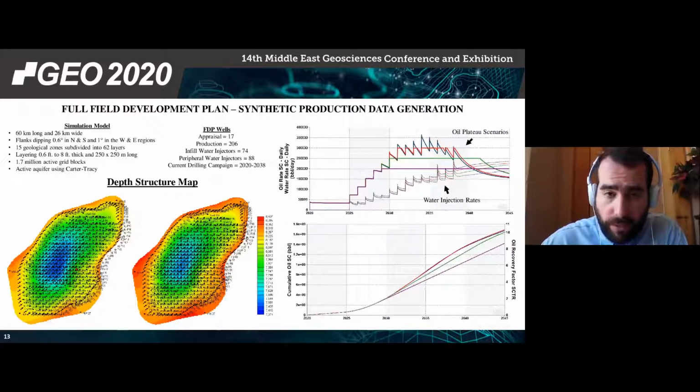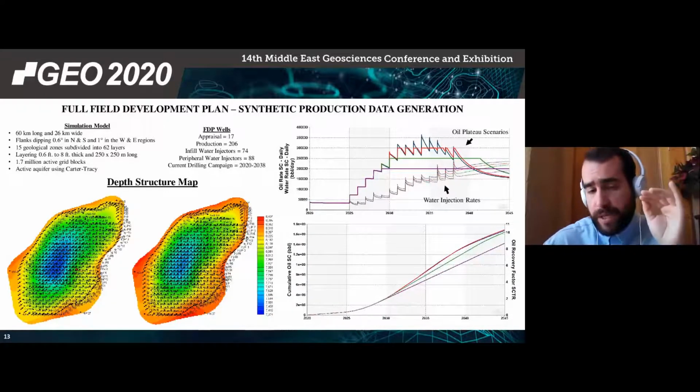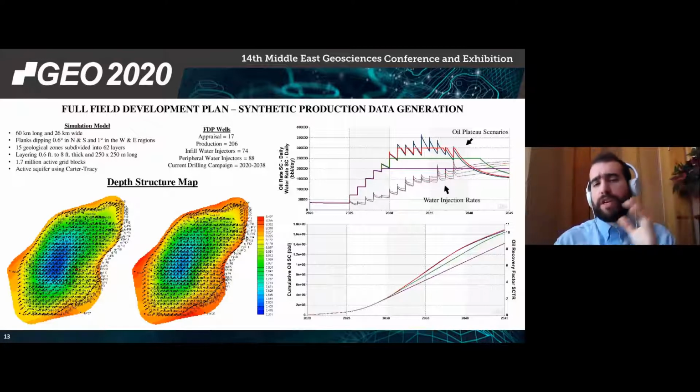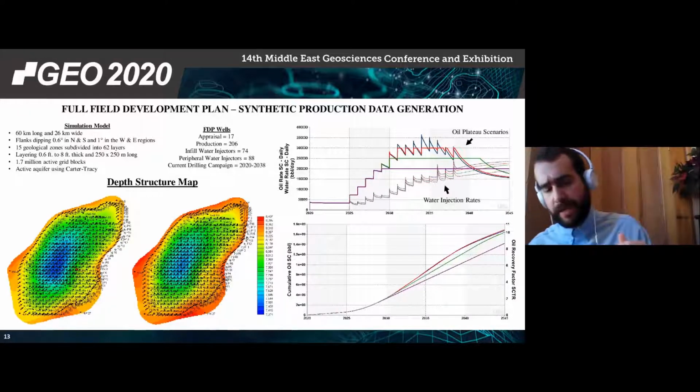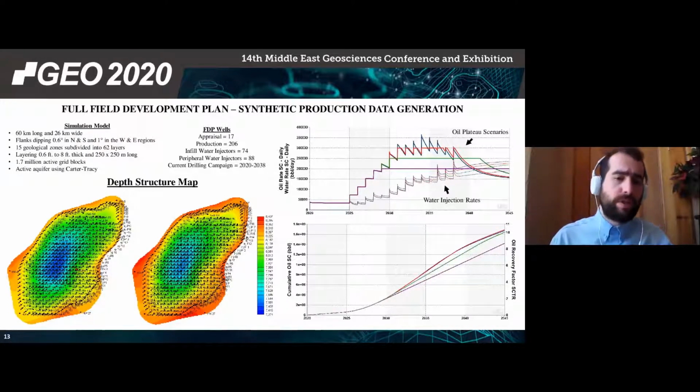So I'm looking at the oil rate plots here, and the solid blue curves are a case where I'm just allowing the rates of the oil producing wells to be at 5,000 barrels a day and to produce no less than 300 psi above the bubble point. So it's a very conservative plan, 300 psi above the bubble point, just to be on the conservative side.